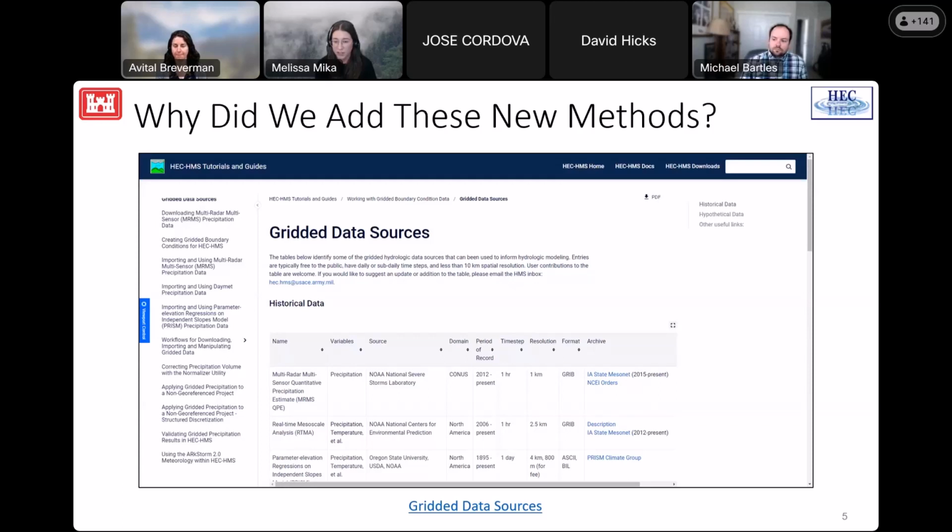And then AORC is one of the most trustworthy data sets that has an hourly resolution, but it only covers 1979 to present day. So if we can use these precipitation and or temperature data to infer these other boundary conditions like relative humidity, we can use physically based land surface methods for many more time periods and locations throughout the world. And this is pretty much how every single hydrologic quantitative climate change study is performed at a reasonable spatial resolution.